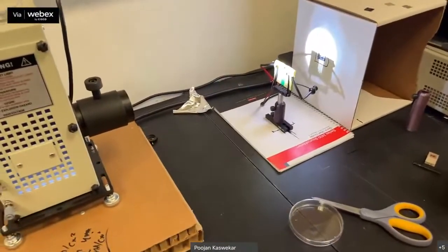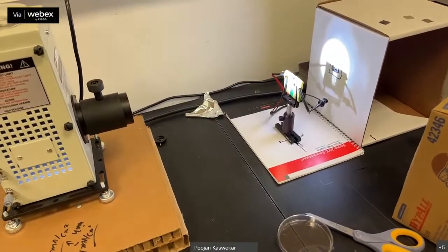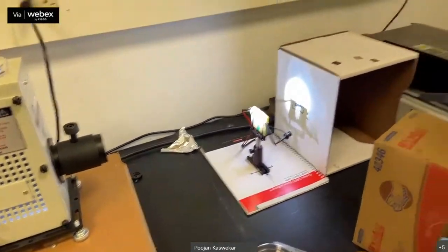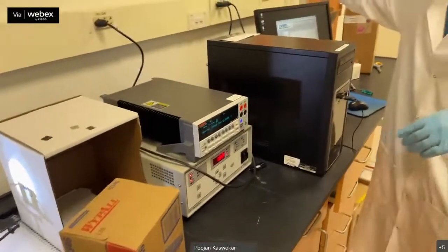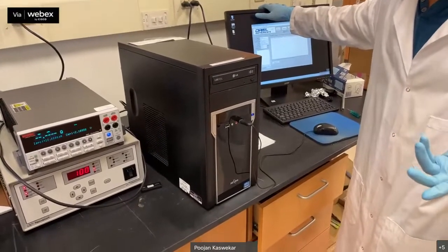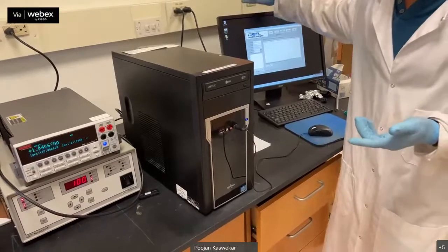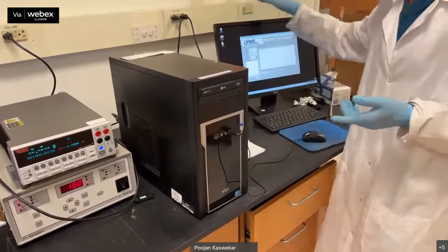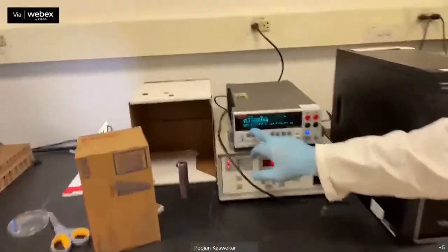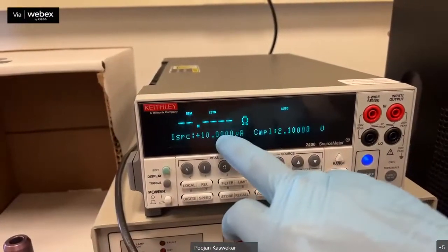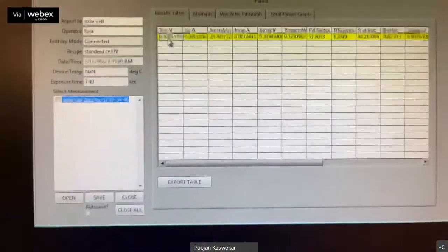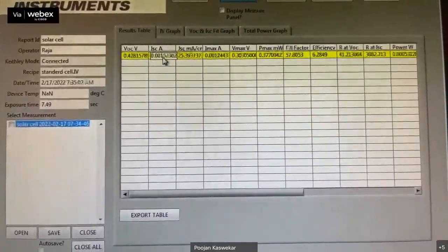So once this is set up, you're just going to press the measurement. This is connected to the positive and negative lead. This one is going to my PVIV instrument, and the PVIV instrument is connected through RS-232 communication. That communication is going to give commands to this system when we need to measure the sample. So once you press measure here, you'll hear a beep sound, which is sweeping the voltage from 0 to like 0.8 to 0 volts.